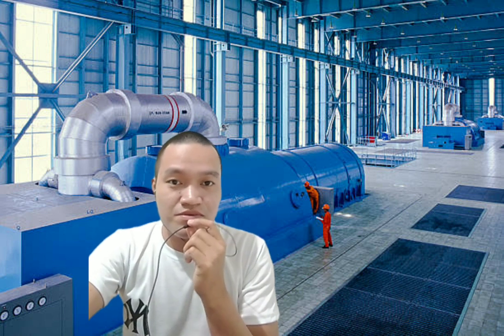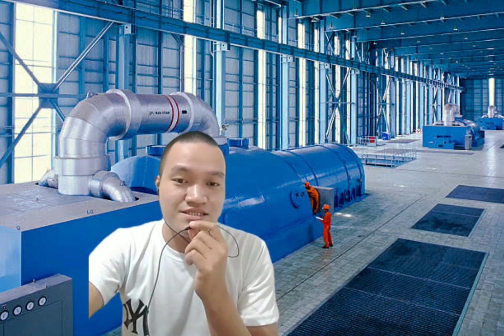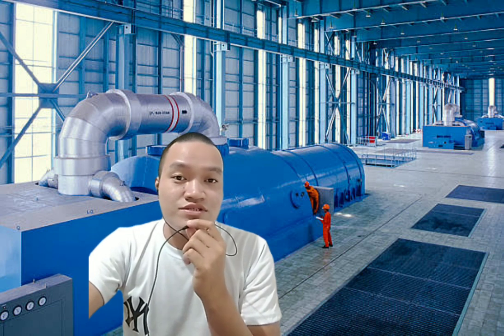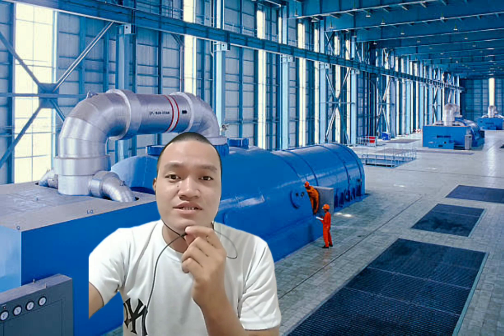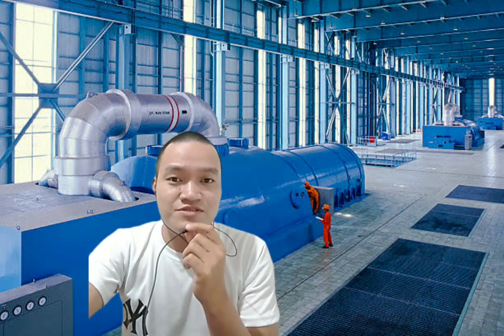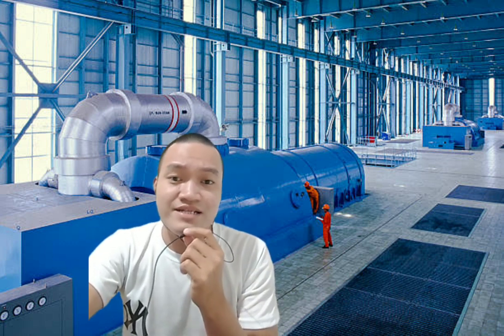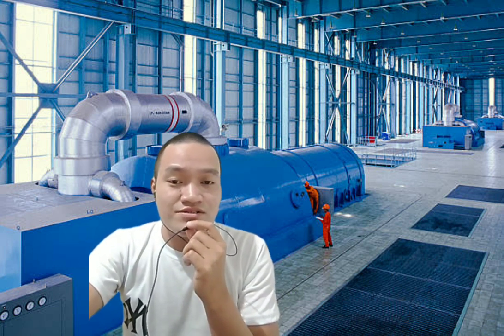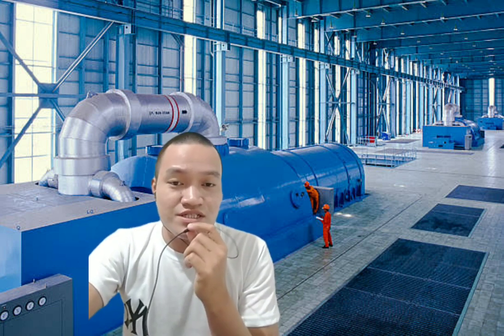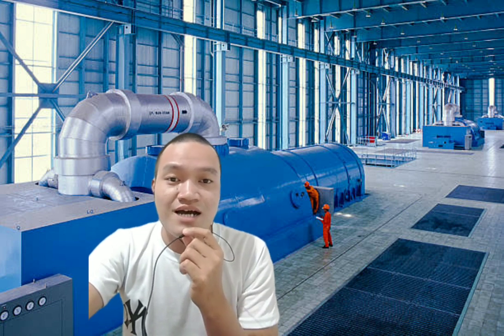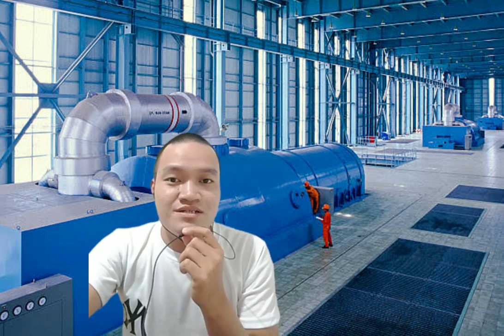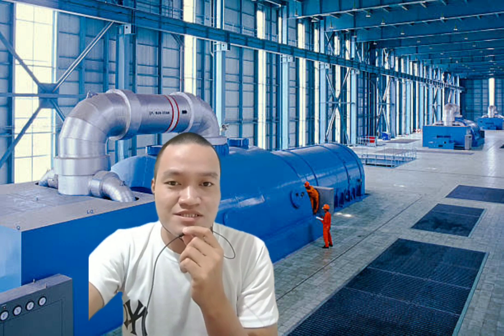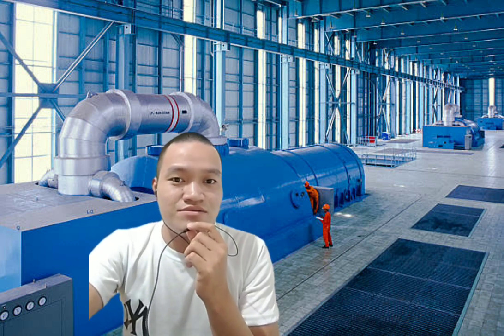Pressure compounding is the use of a number of blades and nozzles to reduce the steam pressure progressively. This results in lower or acceptable steam speed flows and better turbine efficiency, while velocity compounding is the use of a single nozzle with an arrangement of several moving blades on a single disc. This results in poorer turbine efficiency, which would be acceptable in an astern turbine.